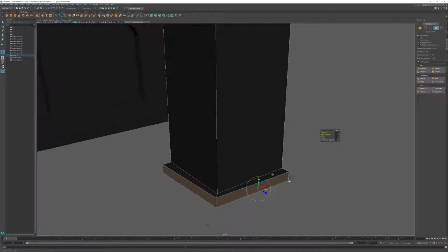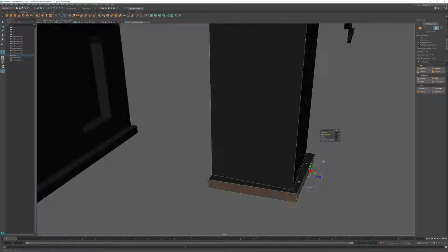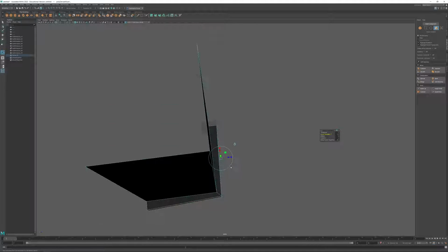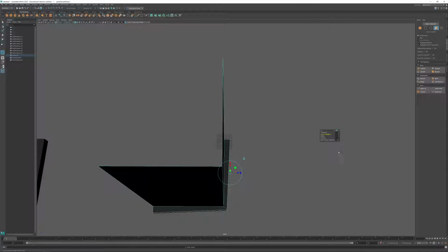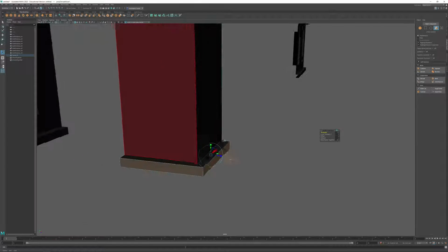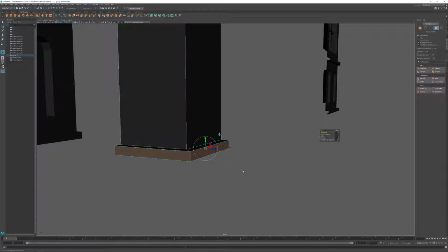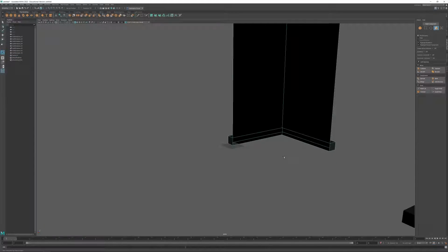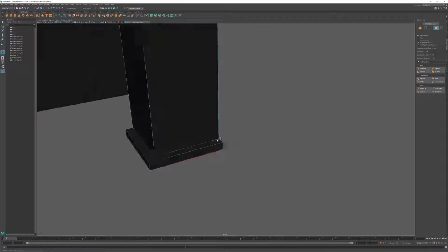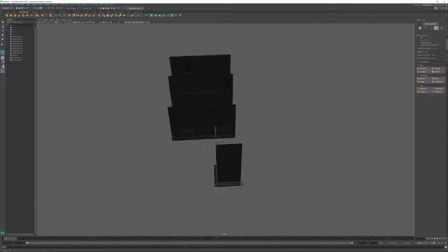Another really good reason to use numbers that you're paying attention to. Now it looks like it's actually skewing on us here when we're doing this. So I'm going to undo that and let's try the thickness here at 12. And now we have nice, stable corners. Excellent. I will delete what is not seen. In this case, the two ends. And now that is corner number 2.